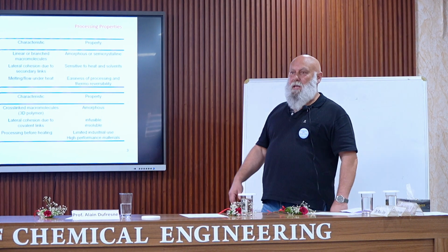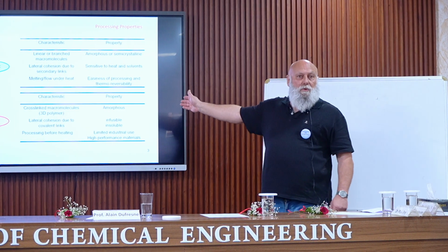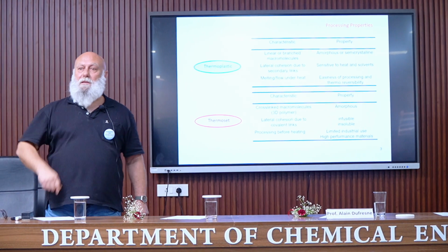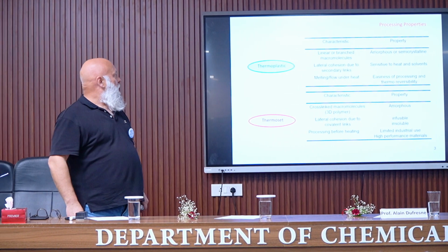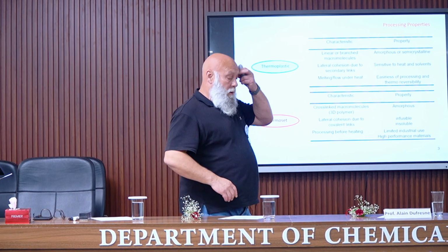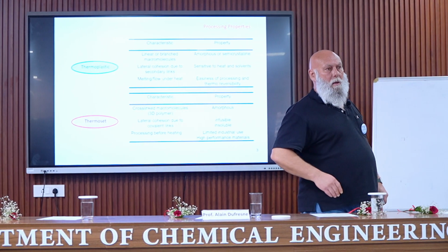Sensitive to solvents. So solvents are molecules which are equivalent to plasticizer. Short molecules with a good affinity with the polymer, but in this case, the solid content or the polymer content is much lower, meaning that the macromolecules are completely separate and they are dissolved.